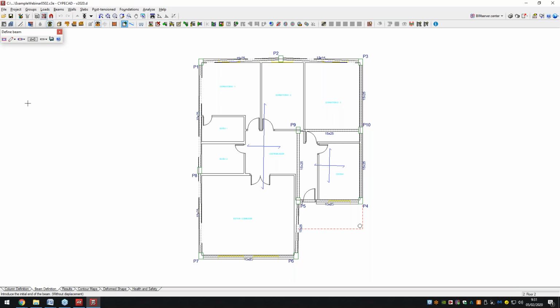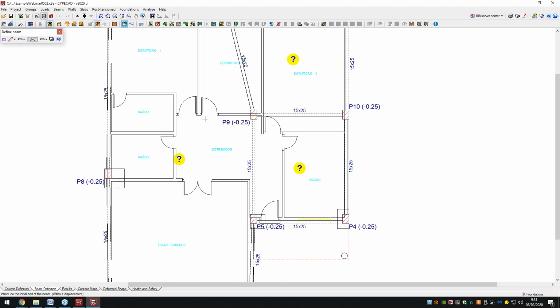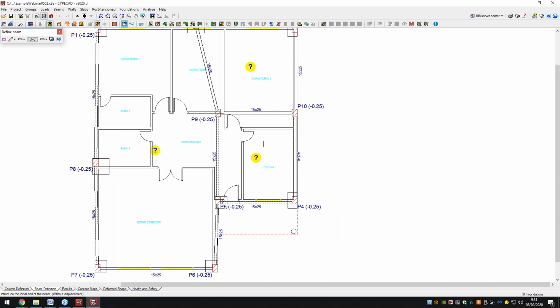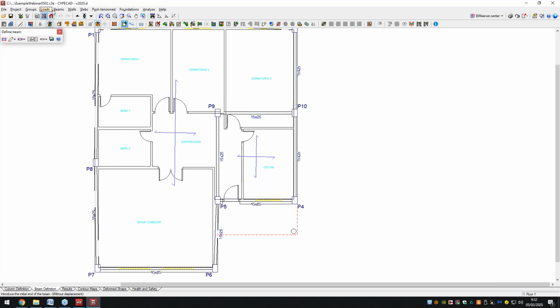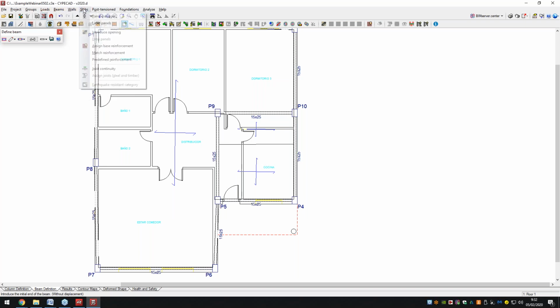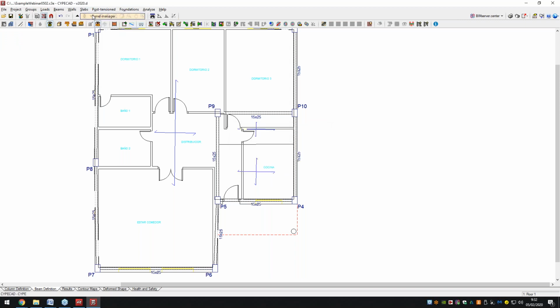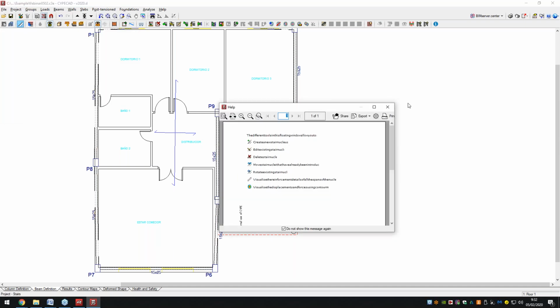Now, of course, if we want to introduce stairs sections as well, we also have our stairs generator here. So what I'd need to do, we could go back down. Now, of course, we don't have the beam here, but I can go up. I can create a different beam. My fictitious slab here. Go to slabs and introduce an opening at that particular section, or go to slab, panel manager, and delete this panel here, and there I'm able to create a definition of stairs here as well.